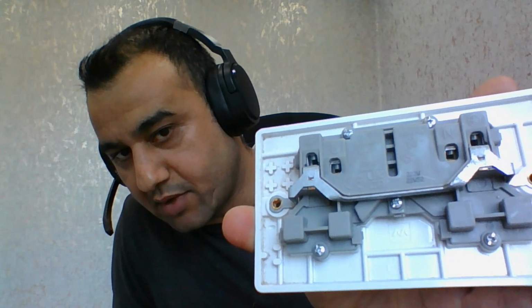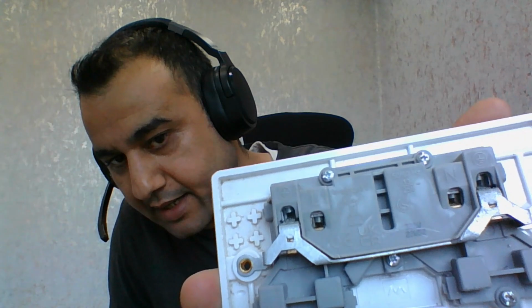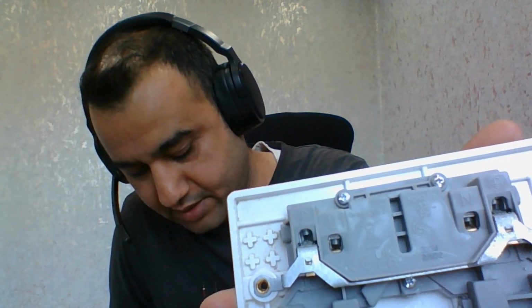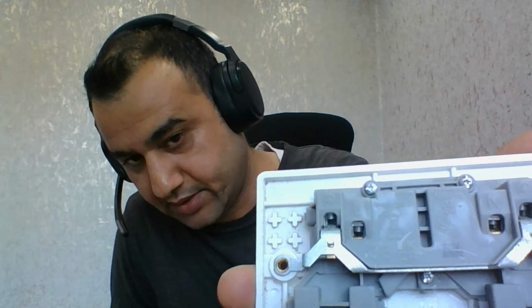This is the one end that's going into the consumer unit, and the other end is probably going to your switch or socket. It depends what you have on the other end. Sometimes you have a fused spur, sometimes a socket, such as this one. If I show you this socket, we can see it clearly here. It does say L, N, E. The brown cable goes in the L, line conductor terminal, and N is neutral. The blue one is the neutral.